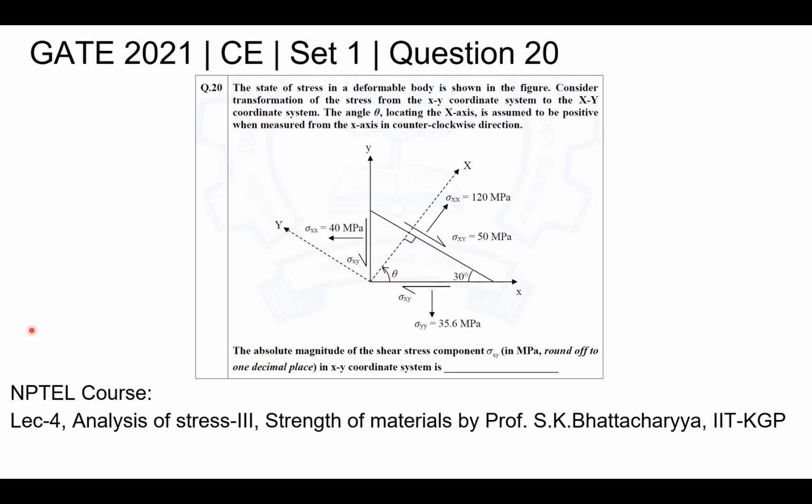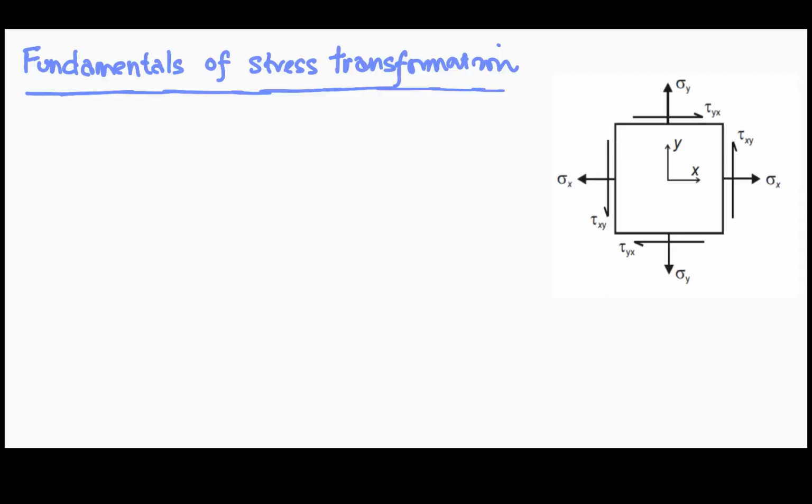Students are also encouraged to watch the NPTEL lecture cited below, where this concept is handled in more detail. However, we will be looking at some fundamentals related to stress transformation as we go on to solve this problem. Let us look at some fundamentals related to the stress transformation. Consider a stress element as shown, with the normal stresses applied in the x and y direction to be tensile and the cross shears to be positive.